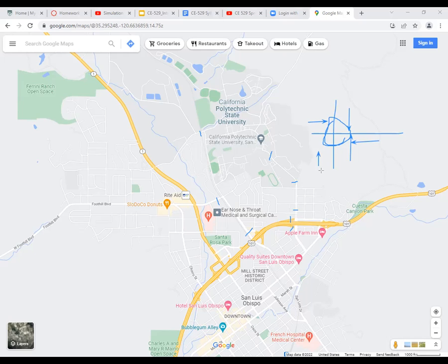So you have what we call the origin destination flows. It's very easy to get that if you're just modeling one intersection. But as you model a larger and larger network, figuring out how much OD, origin destination flow there is, can get complicated. Simply having the AADT, the average daily traffic, or even peak hour traffic volumes at the marked locations I was showing you earlier, like here, here, here, might not be enough by themselves.